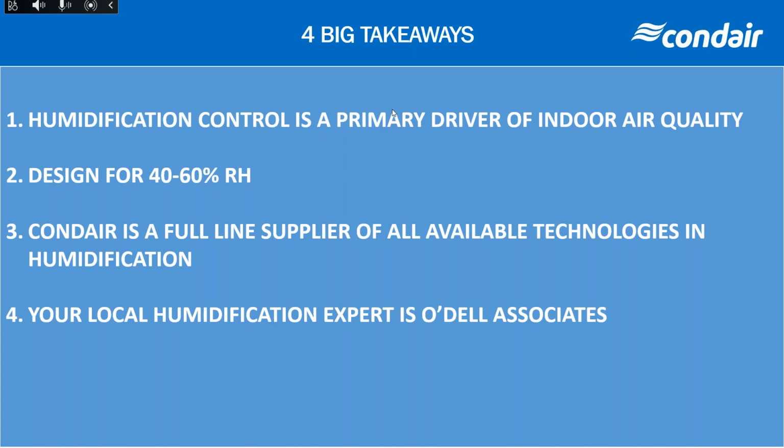So the answer is yes, and there should be caution made in where you put supply and return air. But I would say that supply air is likely more important than return air, because my analogy is always, it's very difficult to suck out a match. So return air is not as critical as supply air, but maybe Dr. Taylor, if you have anything to add to that.